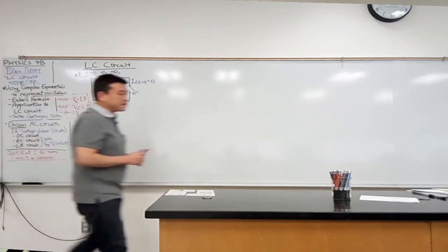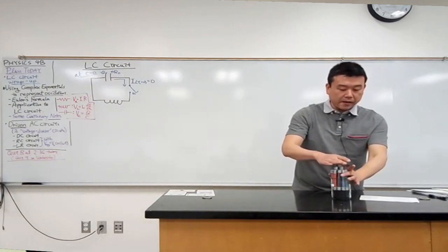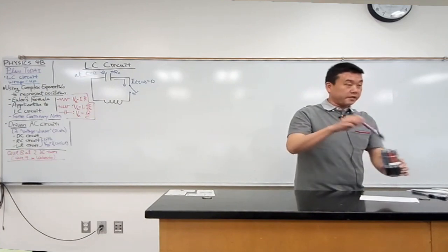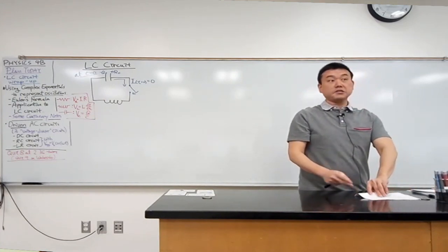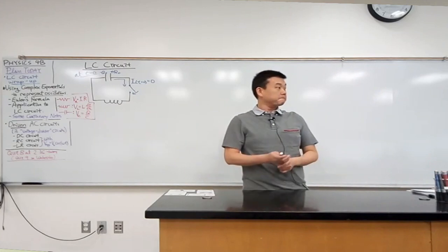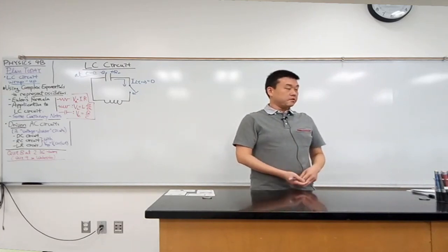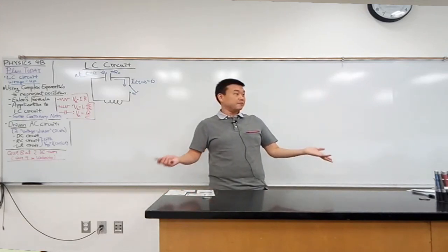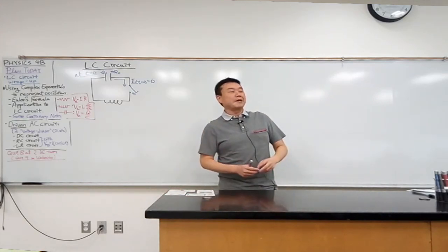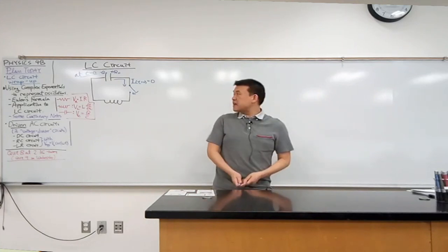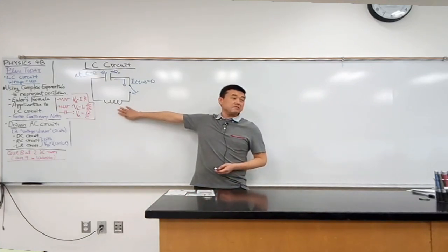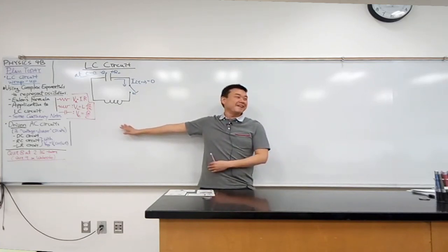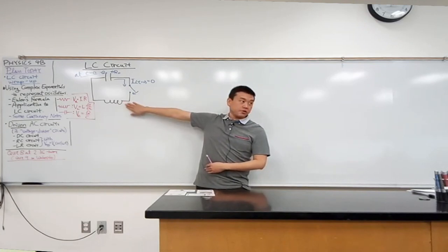So when you're trying to analyze a circuit that you haven't seen before, where do you start? Like, what's the general purpose tool that you have that will let you analyze any circuit that you see for the first time? Yeah, Kirchhoff's rules. So there's the loop rule and junction rule. And with the DC circuit, we used both sets of rules because a DC circuit is simple, so we can make the circuit more complicated. As we're dealing with this time-dependent circuit, because there's only a finite amount of time in the world, in class and during the exam, I'm going to give you a simpler circuit.